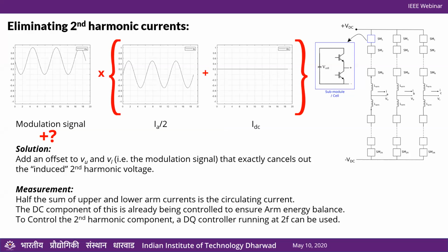So if you have devices that can operate at 1200 volts or 600 volts or whatever your system requires, then just use those. There's no reason to add more complexity, because if you have n modules, you need n isolated power supplies to drive the gates. You need sensing. You need gate drivers. There's so much more complexity, right? So nobody is going to select this just for reducing harmonics.